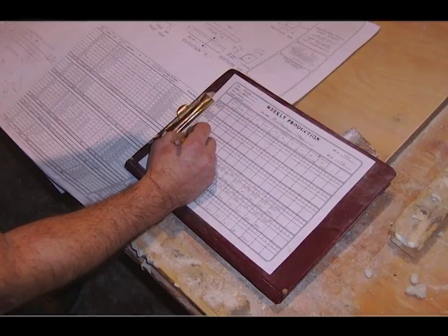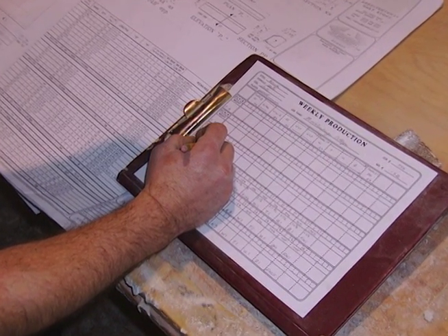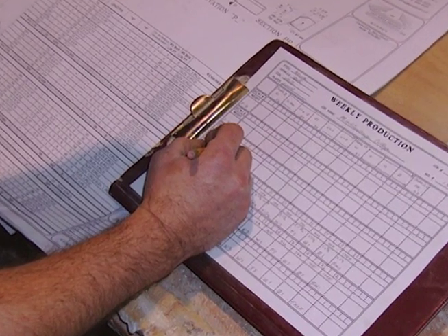The Cast Stone Plant Certification Program really is an intensive qualification, if you would. In order to become a certified plant, a member must pass an 88-point plant inspection. It certifies everything from their production processes to the molds to the raw material, record keeping, testing, and even the product itself. Once they pass the initial inspection, they're even subject to ongoing inspections conducted by an independent engineering firm. These inspections are conducted unannounced, so our members really have to be ready for an inspection at any time. This protocol really helps us maintain the integrity of the system and ultimately leads to a higher standard for our certified plants.